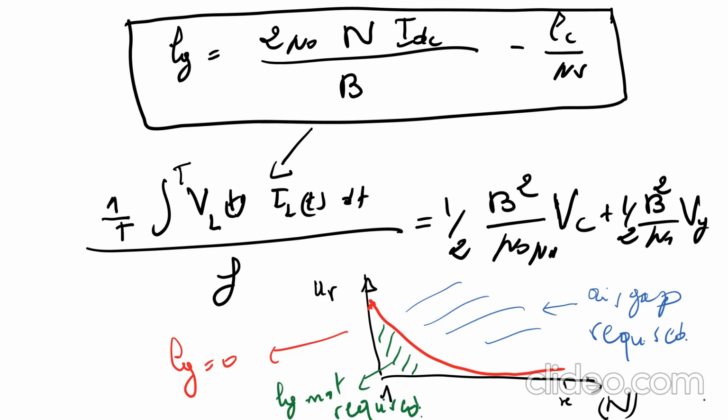It is inversely proportional to the magnetic flux density. The magnetic flux density is up to the designer to fix; it could be the maximum magnetic flux density or the optimal operating B. As you can see here, there is no cross section, and that's the correct equation to calculate your air gap. Now let's try to understand this equation and derive the main conclusions from it.